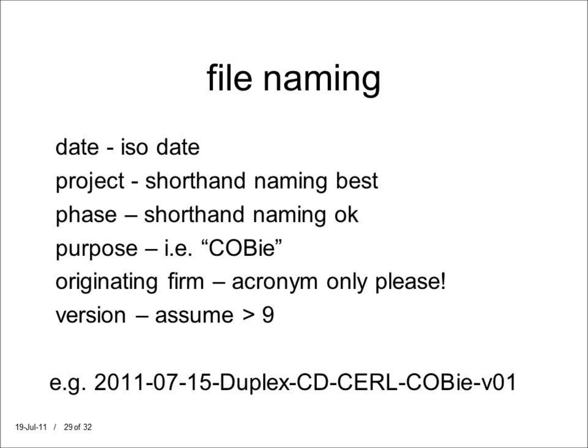And you might also have versioning, and I would assume, just for general purposes, that with some of these files you might get versions larger than 9. And so you might start it with a V and an 01. So if you send it back and forth a whole lot during a day and you get it updated, the files aren't going to display out of order. So this is one naming convention. There's lots of others. You can make up your own on your project.